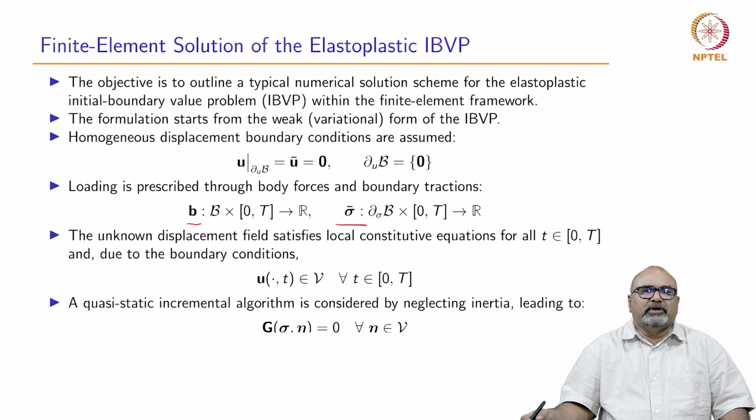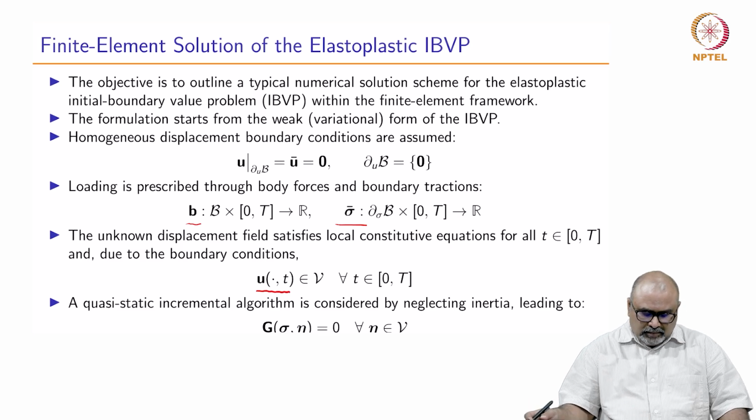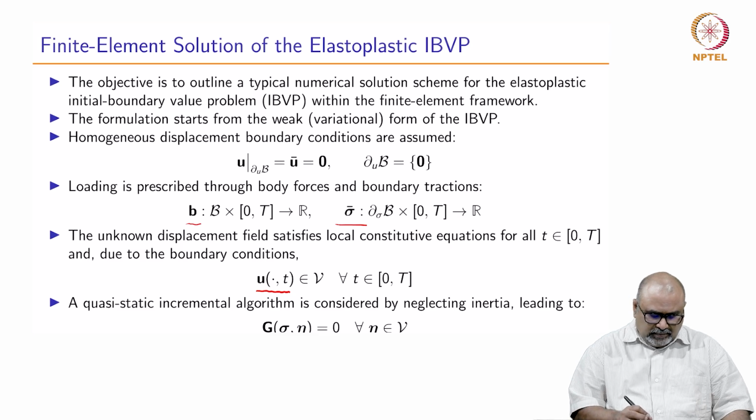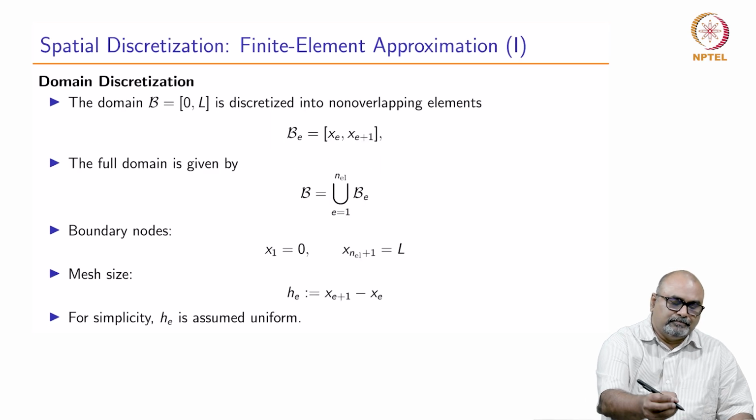The displacement fields satisfy the local constitutive equation at all stages of loading, and the displacement field is given by u comma t. An incremental iterative approach is considered, and inertia is neglected in this formulation, and the quasi-static incremental algorithm is given by g of sigma comma eta must be equal to 0.